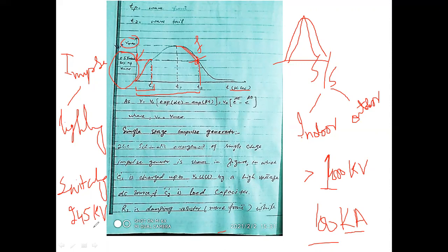Both types of overvoltages are also effective in distribution systems, where they are either produced by switches, or where they have been transmitted from the high voltage system. Here they may often cause a breakdown of electronic equipment as they reach amplitudes of several kilovolts, and it should be mentioned that testing certain apparatus with transient voltage or current is a need of today. Such tests involve electromagnetic compatibility tests, which will not be discussed here.